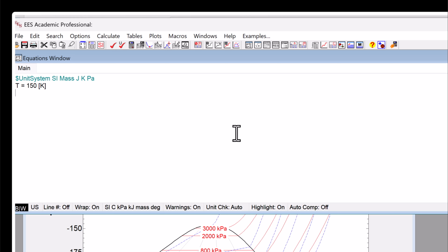And I want to fix the Joule-Thomson coefficient. The Joule-Thomson coefficient is the change in temperature that you get as a fluid changes pressure adiabatically, neglecting kinetic energy. So as you go through some flow restriction, it's dT/dP at constant H. So it's going to be in units of temperature per pressure. A reasonable set of units here is Kelvin per bar, right? If it's Kelvin per Pascal, it's going to be a tiny number. We'll do Kelvin per bar. So let's set it to something like 0.1 Kelvin per bar.